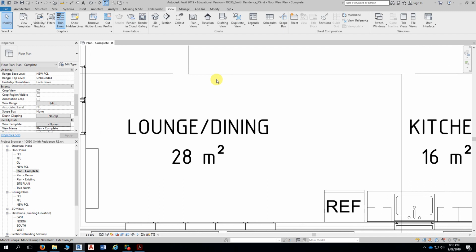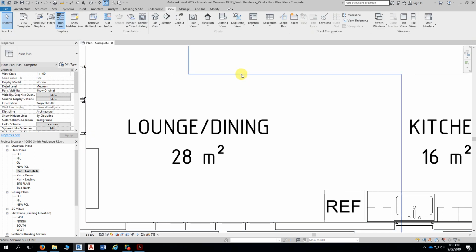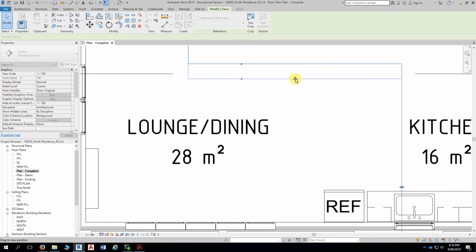So I guess also just make sure that this part of section B, this line running through here, does line up roughly with the line running through for section A. If you have to adjust it, note you've got these little drag arrows, these shape handles, and that can be moved up or down.